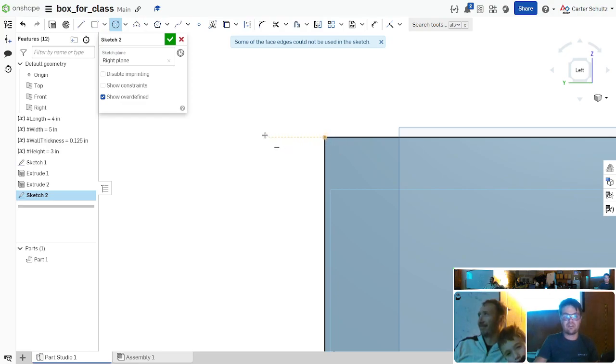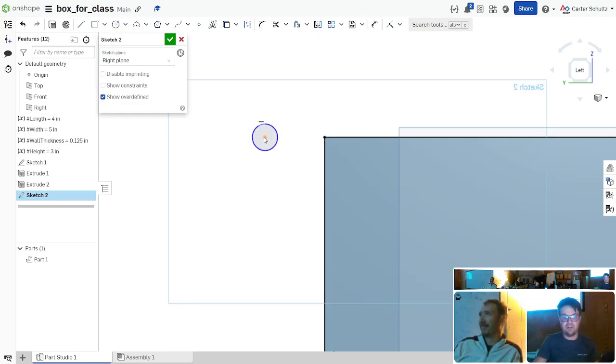So I'm gonna start here, and I'm gonna drag to the side. I'm gonna create our little circle, and our circle, by starting there and dragging to the left, ended up constrained to that line automatically for me. One of the things that you will absolutely hate about OnShape as you go to learn it is that it automatically creates a lot of constraints for you depending on mouse stuff that you do along the way. So if I'm just in space right here, I can create a point and there's no constraints to it, but as soon as I start touching stuff, it starts trying to make automatic constraints. And it's showing me a preview of the automatic constraints it's trying to make as I move this around. But you'll make something and you'll be like, why won't it let me move this? It's because it put in automatic constraints for you.